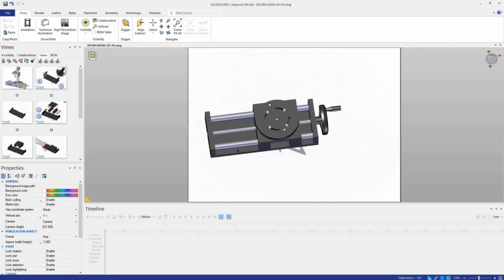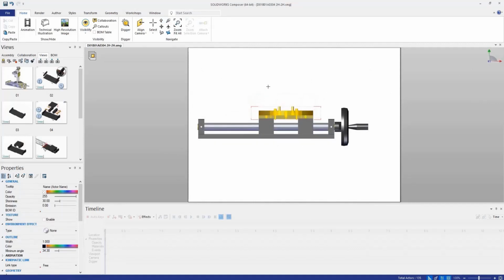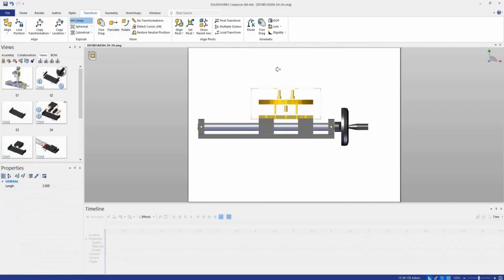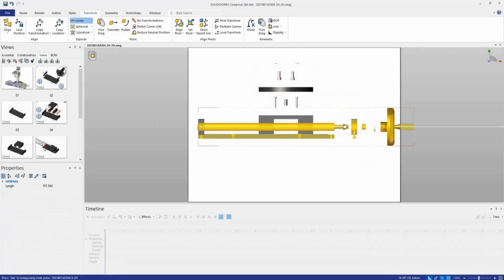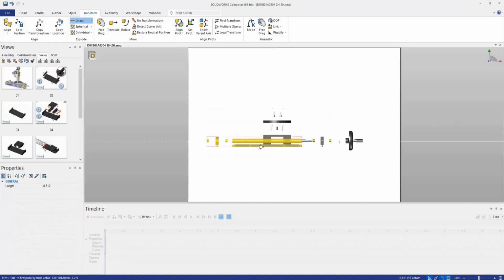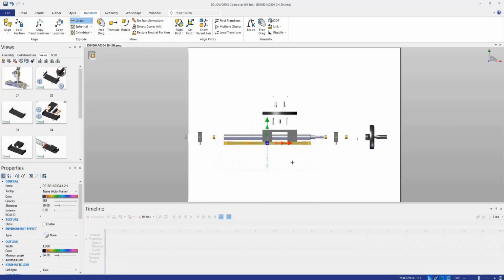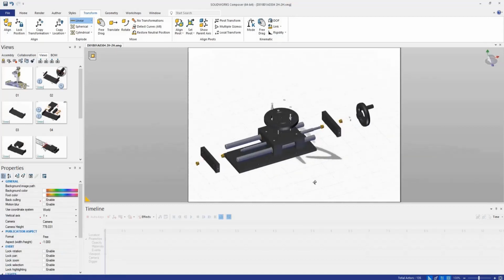So let me do some exercise. Generally, we are creating the exploded view. Okay. So for the exploded view, we have the options available, right? The translate, or you can do the linear explode, spherical, or cylindrical explode. We can simply select all the parts available over there and do it. Simply drag the things accordingly. It will set it as per our position. Okay. Now I think it is best.